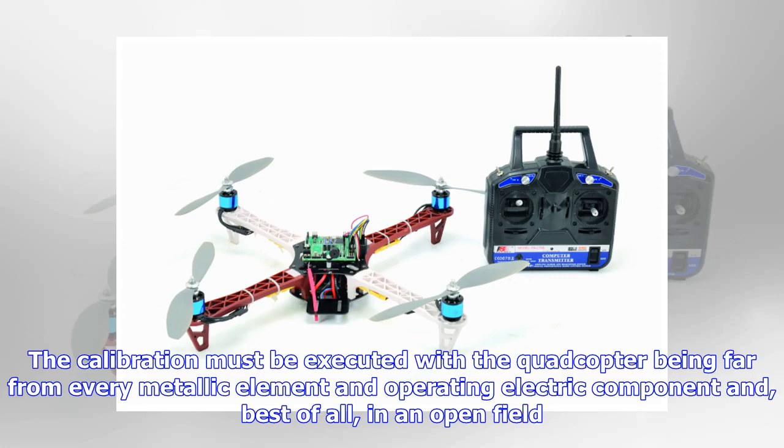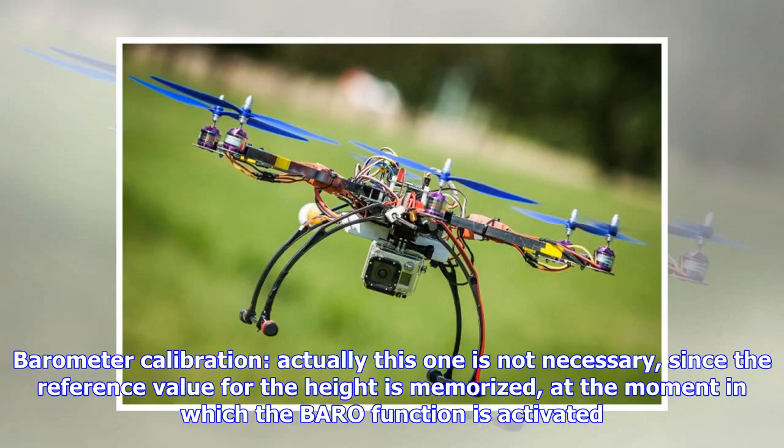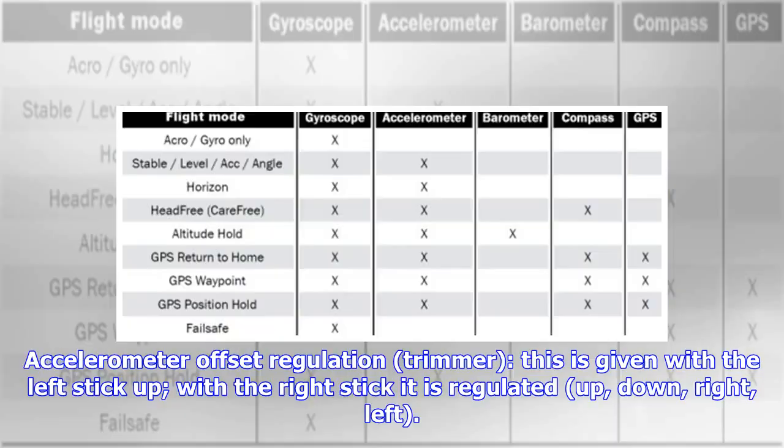The calibration must be executed with the quadcopter being far from every metallic element and operating electric component, and, best of all, in an open field. If you are using the telemetry, the wireless one is better, otherwise the USB cable will get tangled. Parameter calibration. Actually, this one is not necessary, since the reference value for the height is memorized at the moment in which the barometer function is activated.